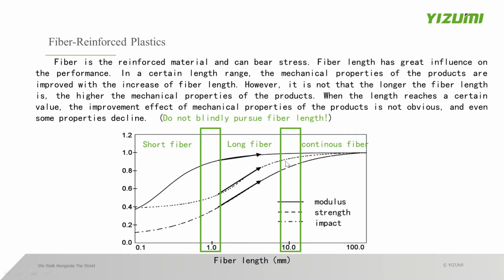Yes, follow the increase, no problem. In a certain range, the mechanical properties of products improve with the increase of fiber length. I think this range is from 0.1 to 10 millimeters. However, it's not that the longer the fiber length is, the higher the mechanical properties of products.